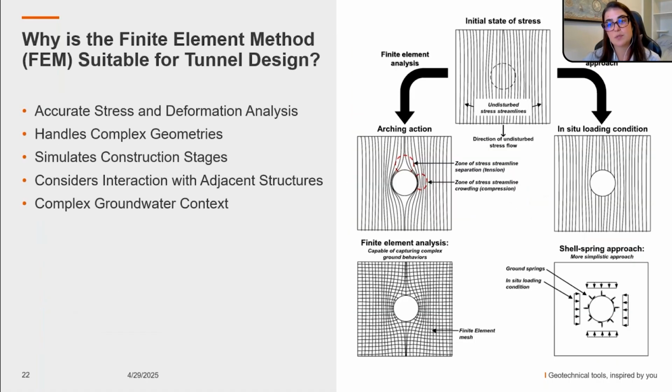So why is RS2 suitable for tunnel design? Tunnel excavation causes stress changes in the ground. These stresses redistribute, creating strains around the opening and loads on the tunnel support. As designers, we need to ensure excavation stability, control ground settlements, manage stress on the linings, and minimize impact on nearby buildings.